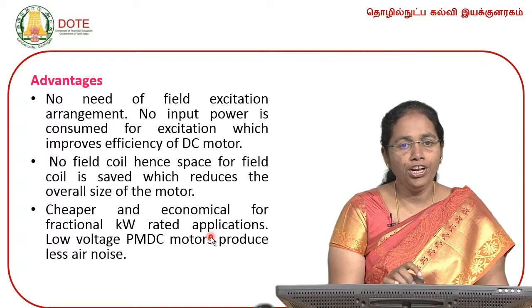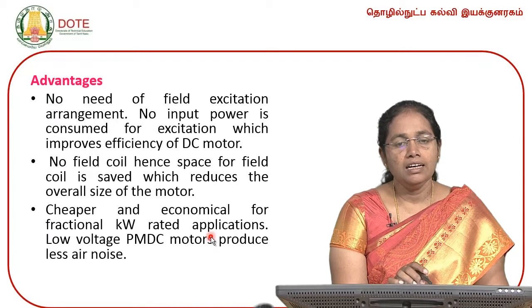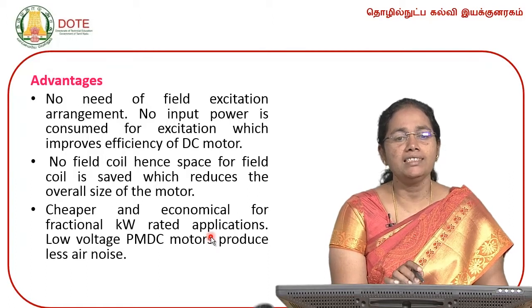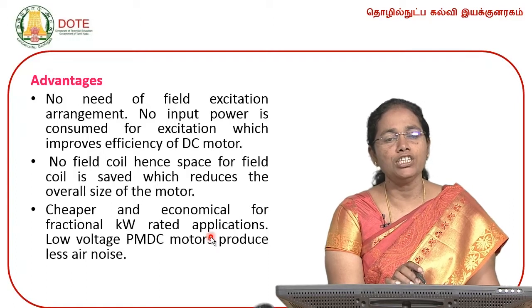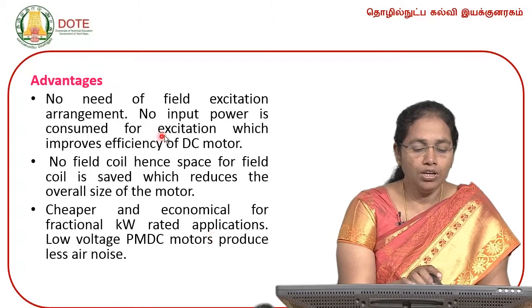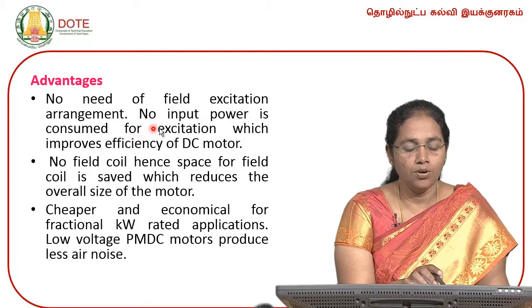Advantages: no need of field excitation arrangement. When you see the other DC types of motors, previously we required a separate excitation, whether it is a self excited machine or separately excited, we have to provide excitation to the field to produce a magnetic field. So, here no need of field excitation arrangement, this is one of the major advantages.